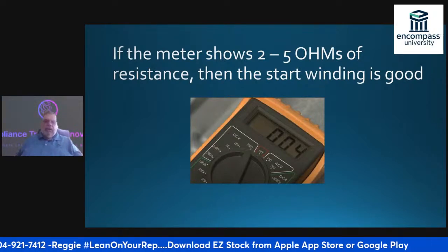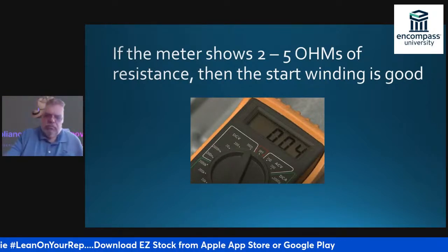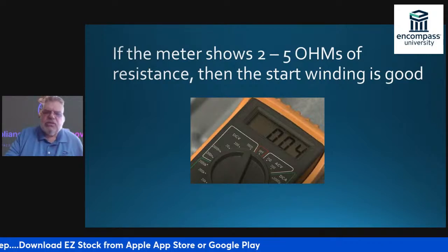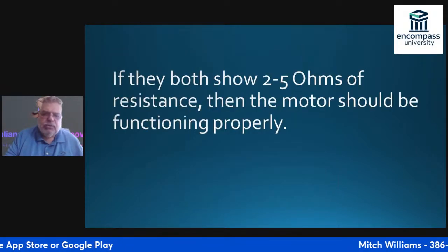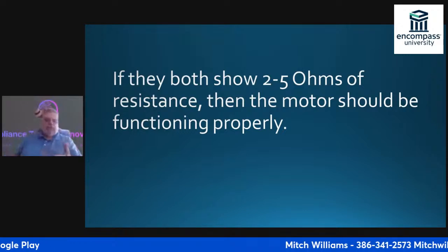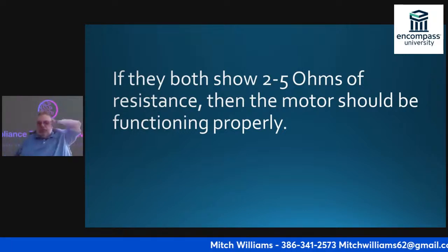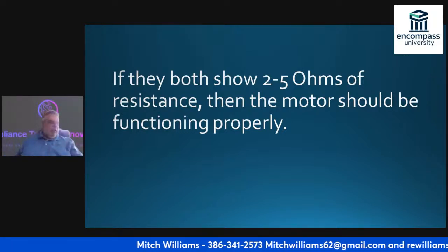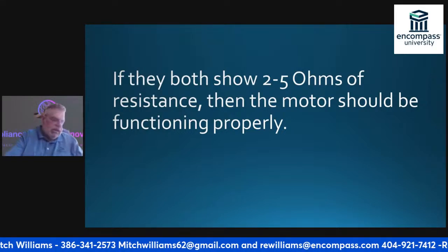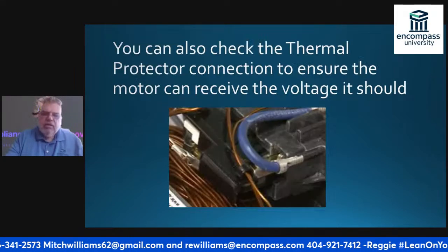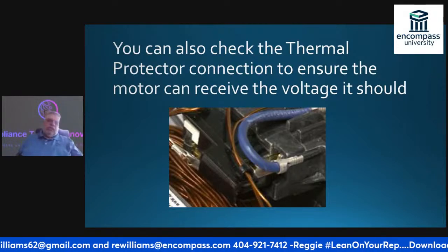that's the run windings, sorry. Then the run windings are good. If they both show 2 to 5 ohms of resistance, then the motor should be functioning properly, and that's if the thermal fuse is any good.